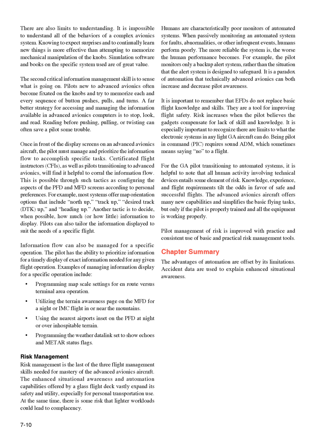When passively monitoring an automated system for faults, abnormalities, or other infrequent events, humans perform poorly. The more reliable the system is, the worse the human performance becomes. For example, the pilot monitors only a backup alert system, rather than the situation that the alert system is designed to safeguard. It is a paradox of automation that technically advanced avionics can both increase and decrease pilot awareness.